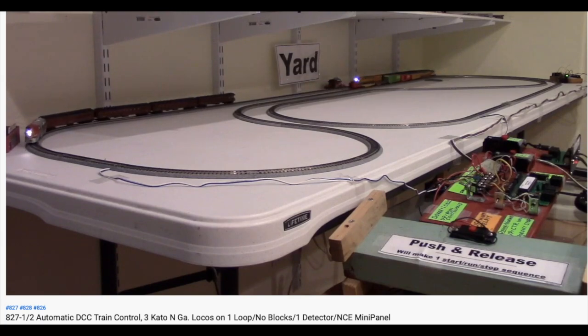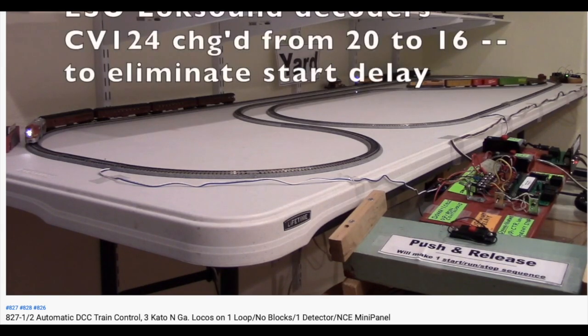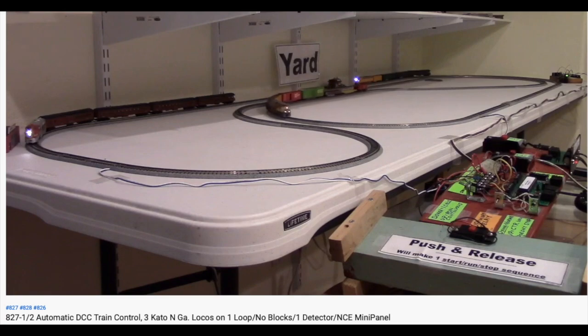We can see now there's 2 trains parked in the yard, and there's a train out on the main line that's working its way toward the detector. And notice what happens when that train crosses in front of the detector. The red Santa Fe, which is in the far left part of the picture, will start up. Here we go. We're getting pretty close to the detector. You'll see that change from green to red, and then the relay contact will close. The train controller will start those 2 trains in the yard up.